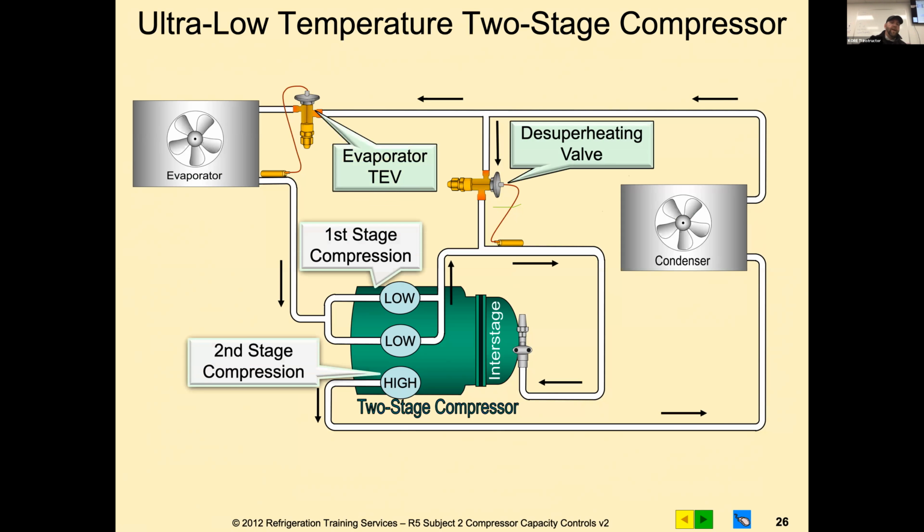It comes in through the bell end and then goes out. The discharge line on these compressors will come out of one of the heads, with a king valve on the high stage. The suction actually pipes into a king valve right in front, then splits off into the low stage, and pipes off the back side of those two heads and into the bell end of the compressor.